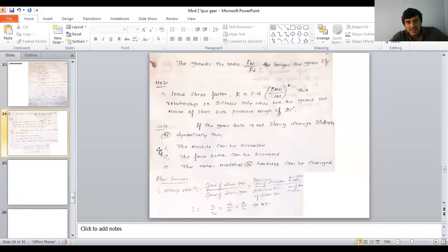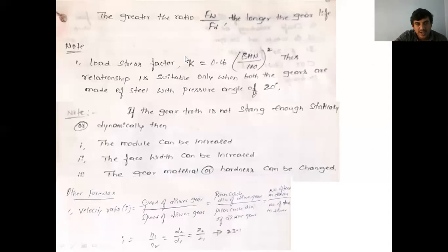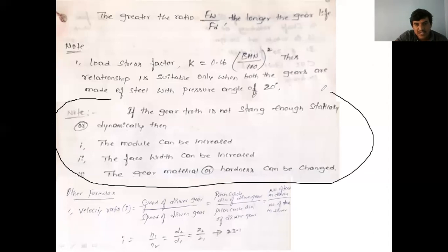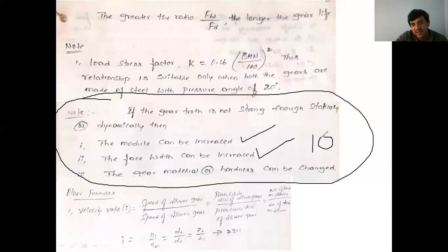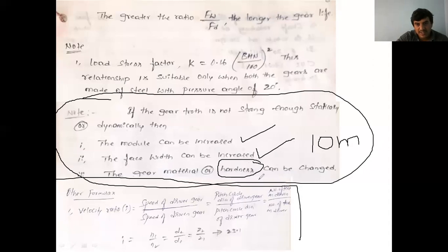After that, these are some of the notes you should remember. If the design is not satisfied, then you change the module, increase the module, and face width also. Once the module increases, face width also automatically increases, because face width is some times the module. Otherwise, you change the gear material, or the hardness may be improved. BHN value you improve. And a very important formula is...